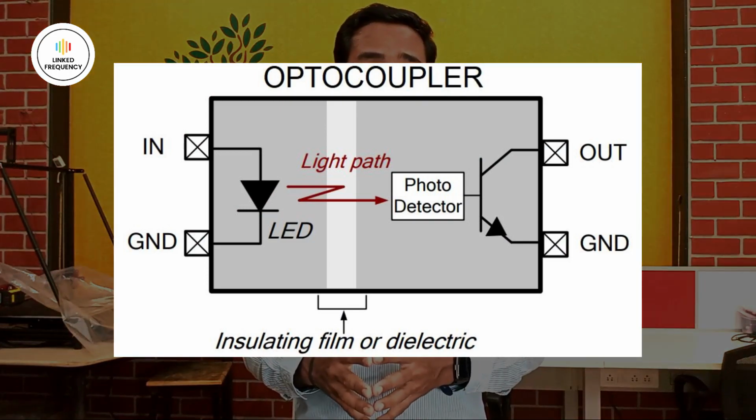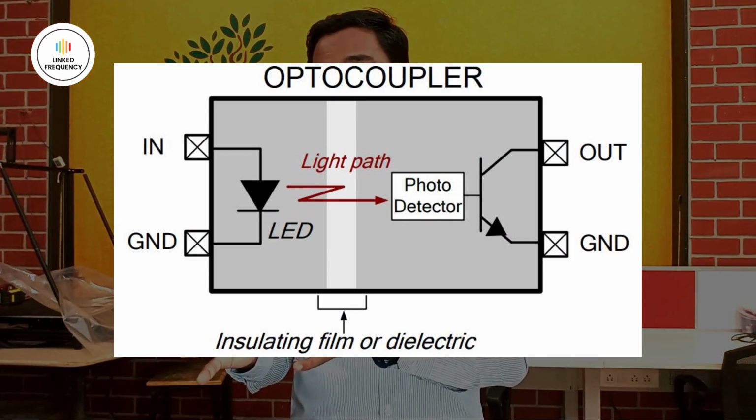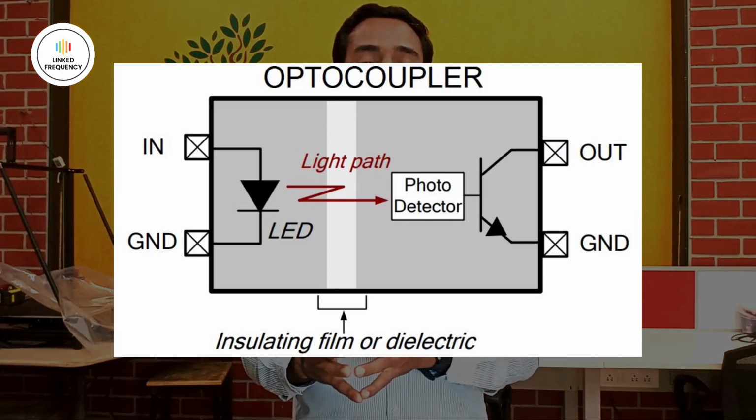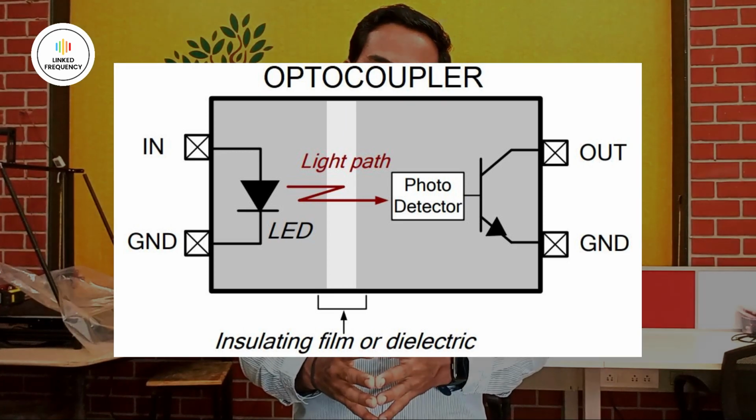At that time, we have to carefully select a relay which has the capacity to switch with a voltage of 5 volt. Otherwise, we have to use another switching circuit to drive the relays, which are called drivers. For galvanic isolation between the relay circuit and the microcontroller circuit, we can use basic optocouplers because they provide very good galvanic isolation between high voltage relays and the microcontroller circuits.